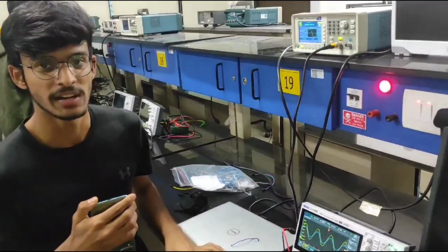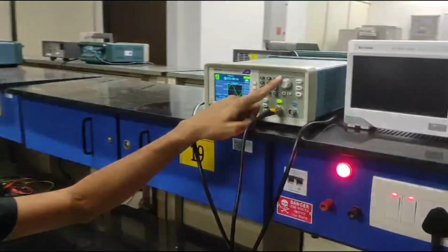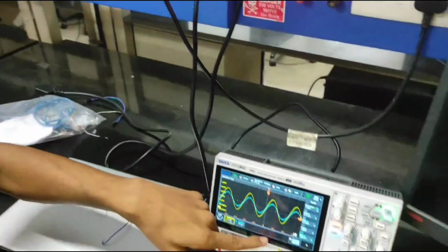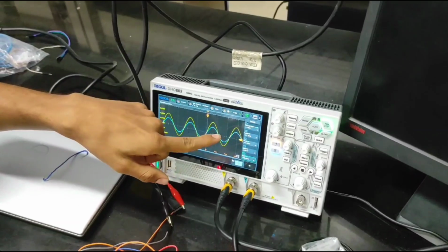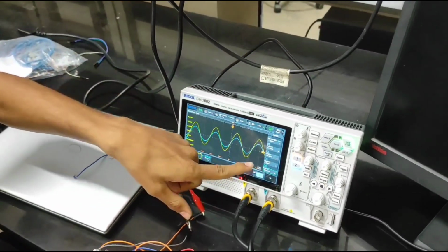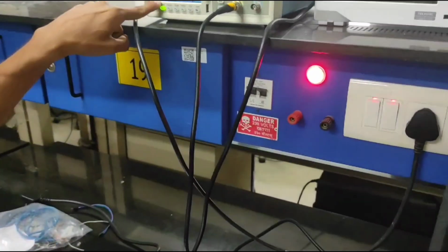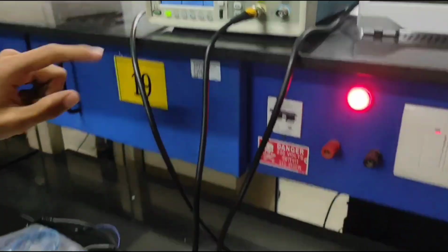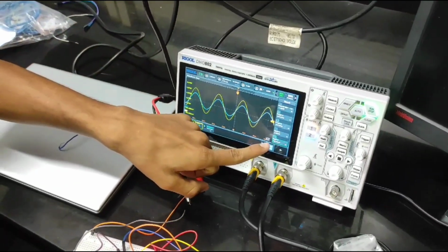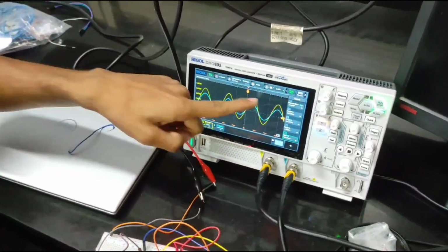Hello, I am Ayush Allad, and in this task we will be varying the frequency using the signal generator in intervals of 10 Hz and see the changes that occur in the output voltage as well as the phase difference. The input voltage will remain constant throughout, as we are supplying a constant 5 volts peak to peak. In this task, we will be seeing the trend followed by the peak to peak output voltage, and also the phase difference between the two channels.